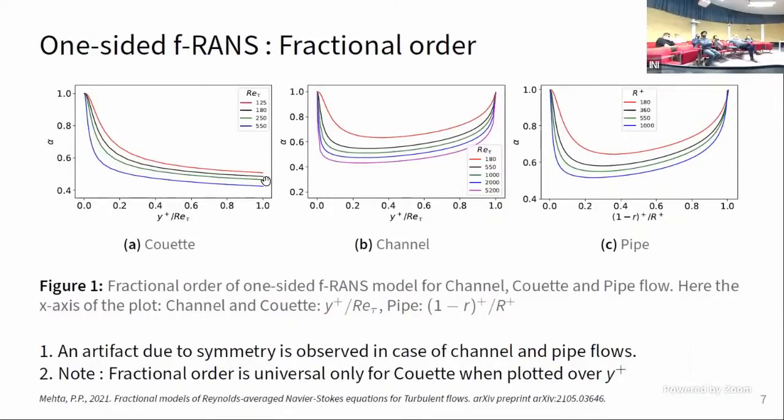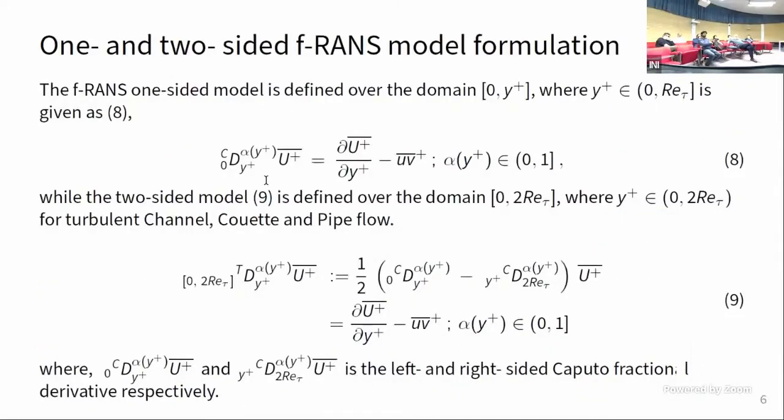So it makes sense that this thin region near the wall is viscous dominated, purely by the local operators. But as we go beyond the wall, non-locality enters, the turbulence intensity increases, and as a result of the turbulence action, the Reynolds stresses are non-zero, and non-locality resides in the Reynolds stresses.